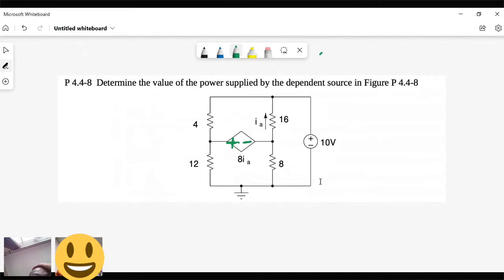All right, so how about this? This is what I'll show you. If you want to do mesh, you draw your loops. So we have one loop here, and one loop there. You see that? So that means you have 3 equations. This one doesn't have a current source. If this guy right here were a current source, then you'd actually only have 2 equations, because that's the way mesh works. So with a mesh, you get 3 equations.